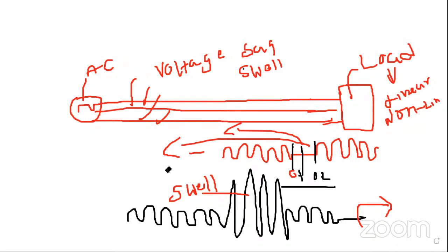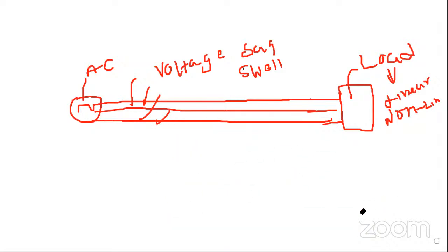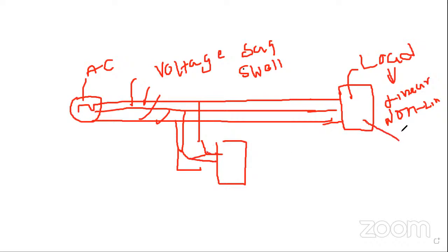For that reason, in the power system network we are interfacing with power converters, implementing integrated power converter topologies. In most cases, voltage source converter devices give a good solution here. If connected in parallel, a converter topology can overcome these problems, harmonics and reactive power. While you are keeping a non-linear load here, reactive power losses will be more.